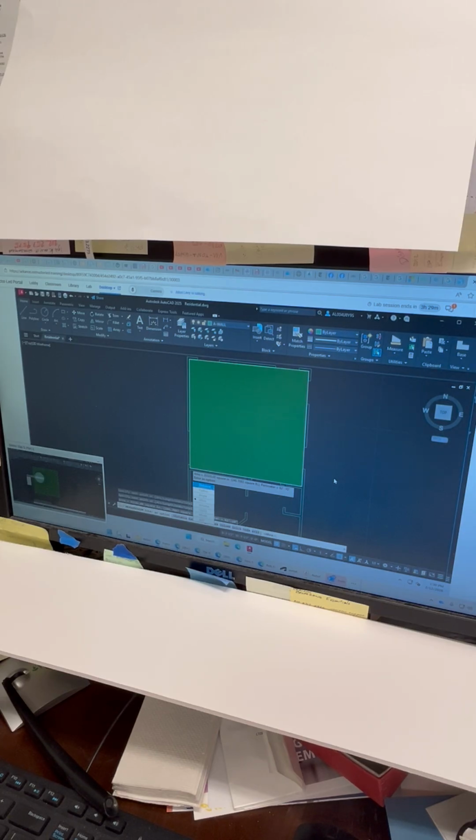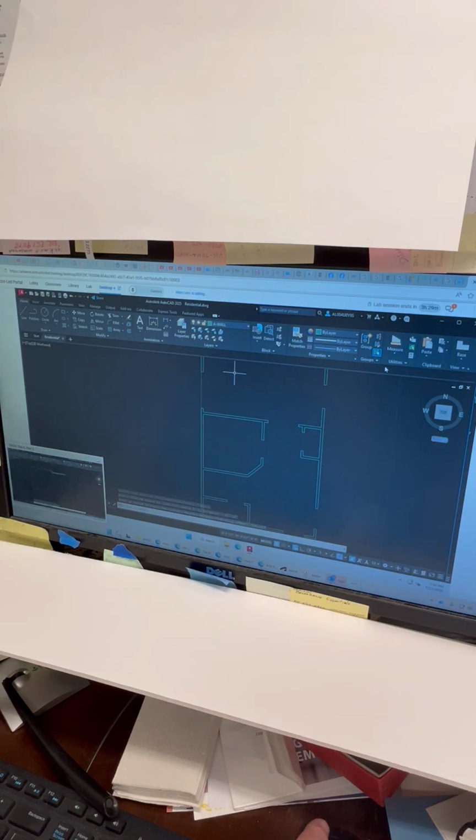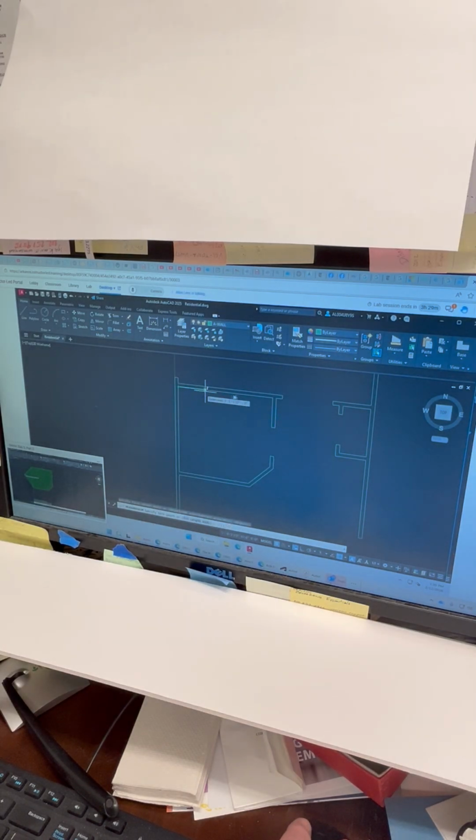All right, let's try another one. I'm going to click area again, sort of refresh it. And how about the walk-in closet? Now this one's got an unusual shape. It's got this little catty corner. So just click on all of the points, just like this. And when you get to the end here, just hit enter. And this walk-in closet is 62 square feet.